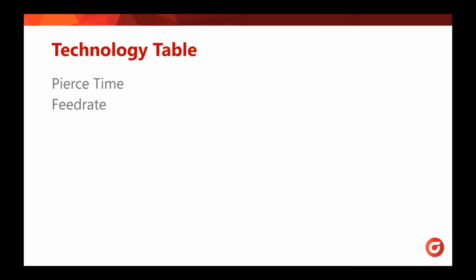Inside the technology table, there are 2 different fields that you're going to adjust that are going to be dependent on the material thickness and the process that you're going to be cutting with. And those are going to be your pierce time and your feed rate. So your pierce time, how long does it actually take to pierce into the material? If you're doing a slow pierce, a fast pierce, or anything like that, depending on your machine, what the capabilities are, as well as the feed rate. So this is going to be based on how fast we're actually going to be cutting, and that will be dependent on the different material, thicknesses, and process that you're going to be cutting.